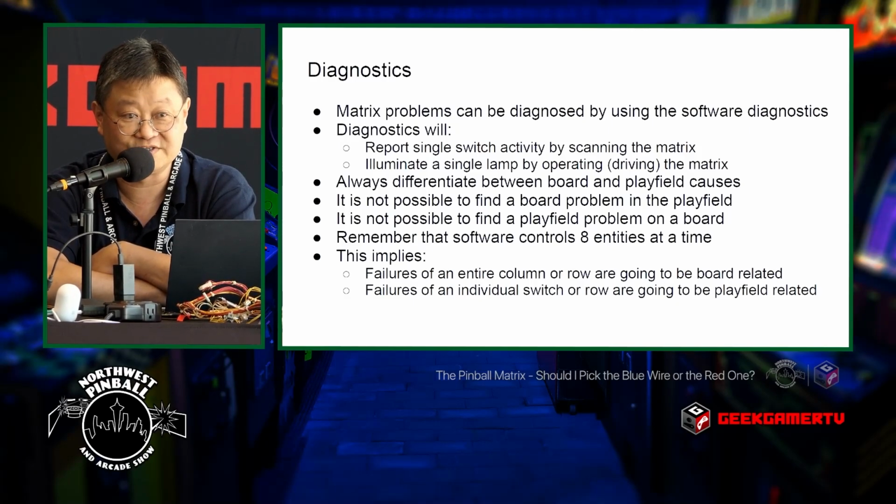If you do not do this differentiation and you immediately assume that it's some diode or wiring or whatever issue, and the problem is on the board, you will have spent a lot of time doing absolutely nothing. Always differentiate between playfield or board. And there are tools that will help you do this. If you don't have the tools, you can use an alligator clip. Run the software test, use an alligator clip.